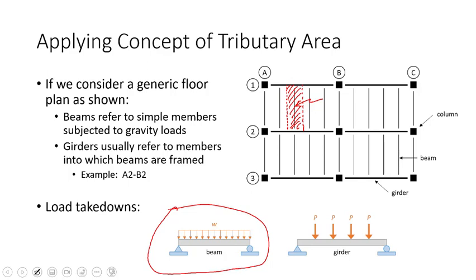Now, that is only under the consideration of a pressure load. In practice, sometimes that doesn't always happen for a couple of reasons. One, there's also the wall that goes around the building. If the edge beams have to support the wall, maybe they end up actually being bigger because they have to support the wall curtain. By the wall curtain, like in this building, I'm talking about the bricks outside the building. You have a 6-inch thick brick facade hanging over the side of the building that has to be held up by something. So that has to be supported by these elements on the edge.